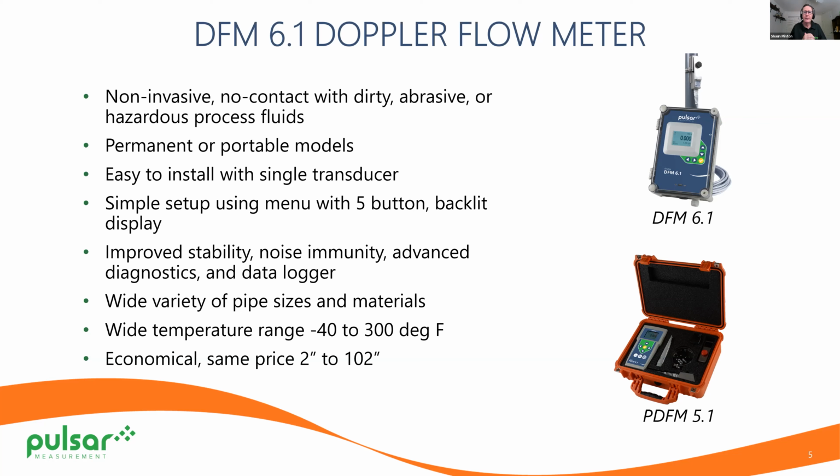The other really cool thing about the Doppler flow meter, and again, I worked for a company that sold millions of dollars worth of magnetic flow meters. The great thing about the Doppler is it does not care what the size of your pipe is. We use the same sensor, whether you're using a 2-inch pipe or a 70-inch pipe. So think about the process of doing an inline system. Again, maybe a magnetic flow meter. You have to cut that pipe. You have to bring in the meter. You have to bring in a lot of people from your company or from your water district, whatever it is, to set that thing up, to get it in place, to flange it, to do all those things.